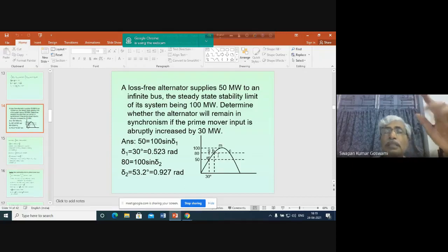And the increased value is above synchronous. So here speed is decreasing, but it is still above synchronous. So since it is still above synchronous, obviously delta will go on increasing further. Okay, and as the speed is being reduced, after this point, sometime here it will so happen that the speed will again become synchronous speed.